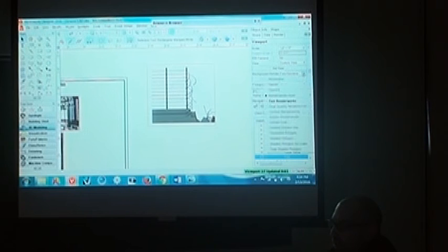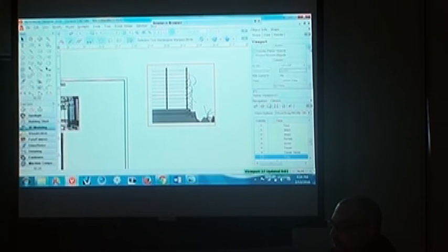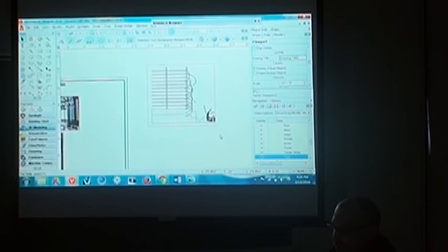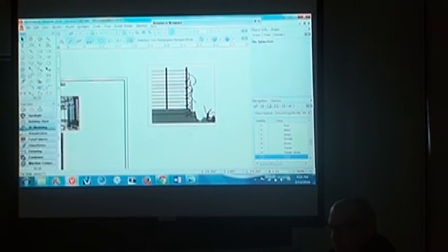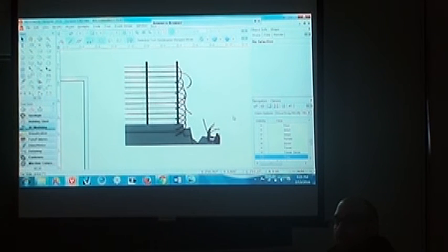I could add a foreground render of hidden line, and that will kind of accentuate the... I lost my background. Oh, background's hidden line. Let's do OpenGL. And by playing with my render mode, I can get an elevation view now of that object that was placed at this weird angle on the drawing without changing anything about it.